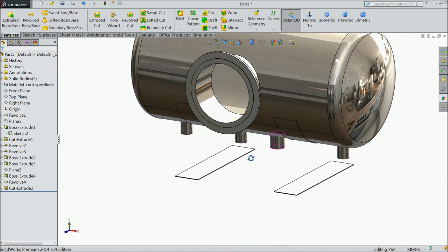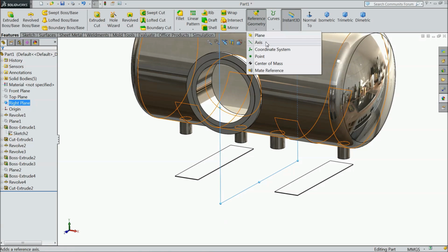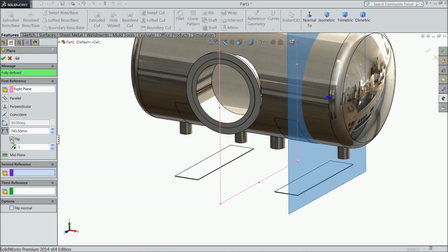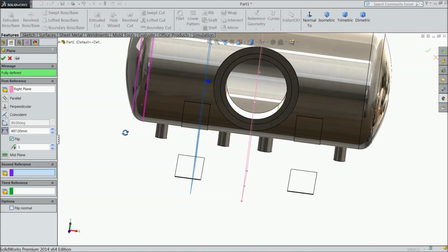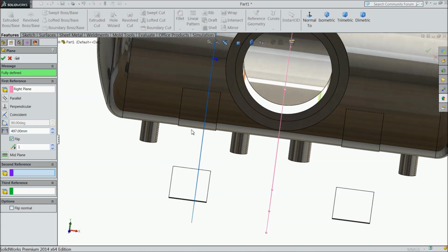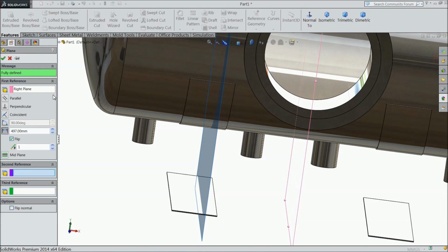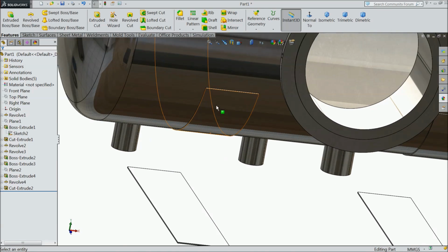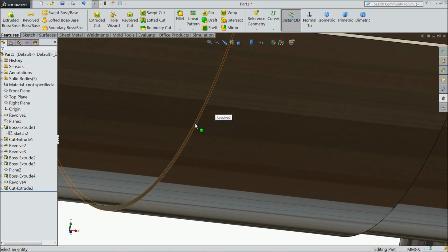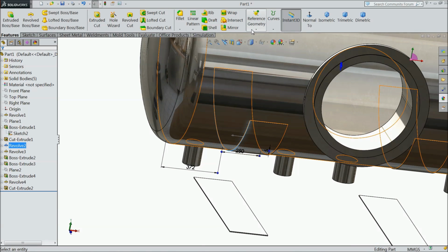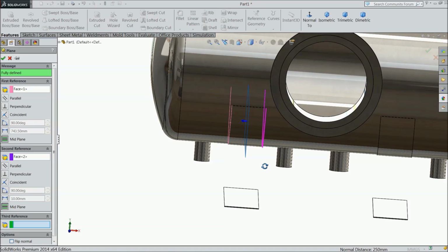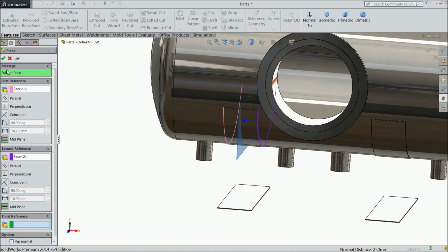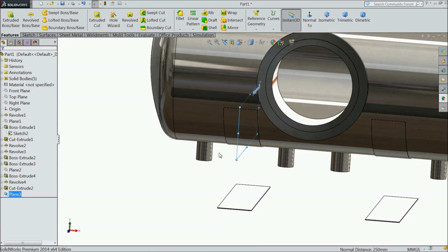Now we will make the base. So first we will do one thing. Select right plane, plane, and we want to create a plane, reverse direction, keep 497 mm. No, we actually want the midpoint for this. So cancel it. Select this plane, and choose this side. So see, it comes mid. Select both the end faces. Okay. Now our plane is created.